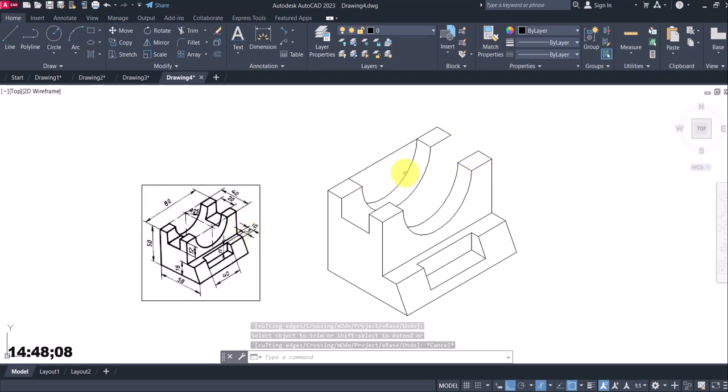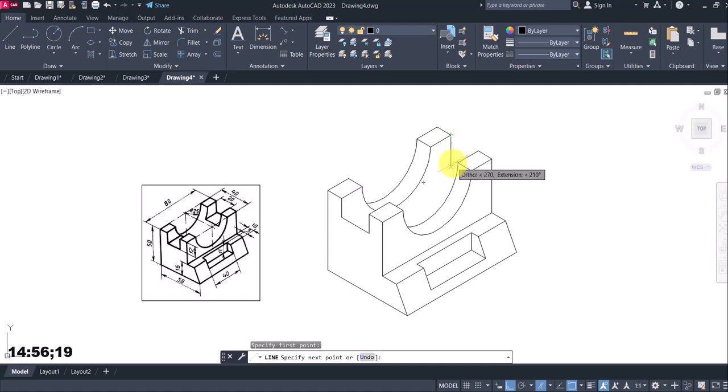Now I'm going to move to this end of the drawing. So line, I need a vertical line of what dimension am I given? Okay, 12. I can see it here, 12. So 12. Then I'm going to change my isoplane, F5.